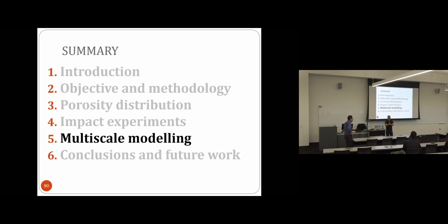Okay, I think this is a very good question. I think this depends very much on the loading path. Because, for instance, as far as we know, for ring expansion fragmentation or the tube fragmentation, the porosity is not good, and under tension this is not working properly. For the small experiments, this is a little bit more tricky because when you have porosity, the porosity dissipates a lot of energy of the compressive wave.